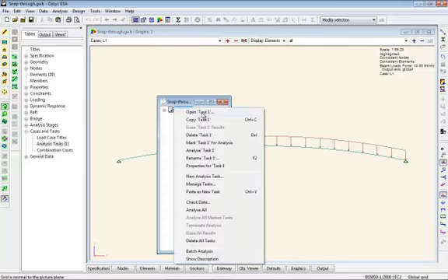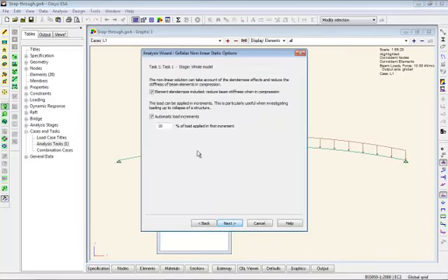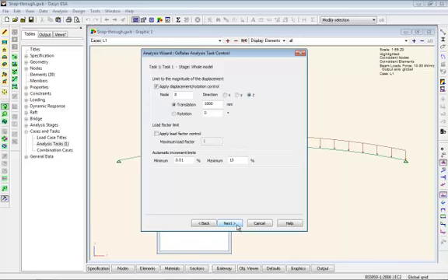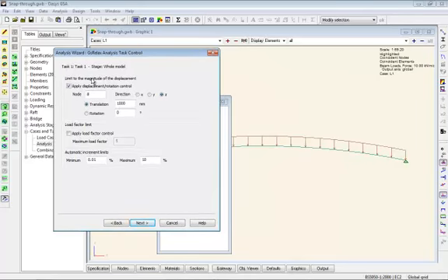So in the non-linear analysis, this time we have automatic load increments set. We'll start off with a low load and gradually increase the load, changing the geometry each time until we get to final failure. The final failure is controlled by this displacement control, node 8 being the node in the middle. I'm saying once it translates more than a meter, then stop the analysis.